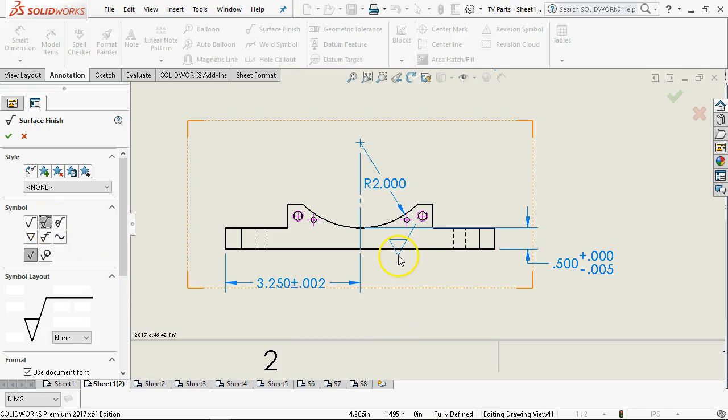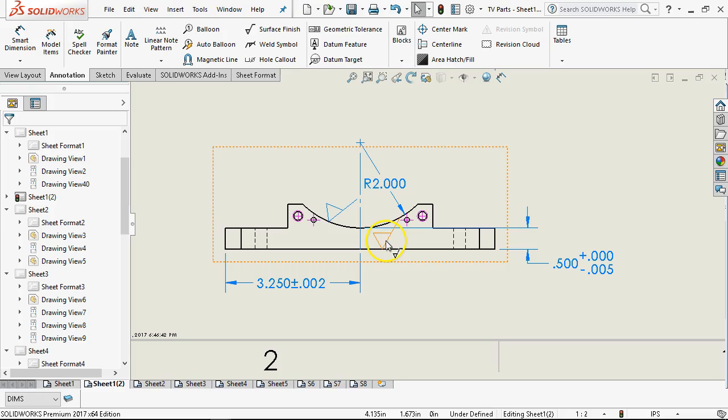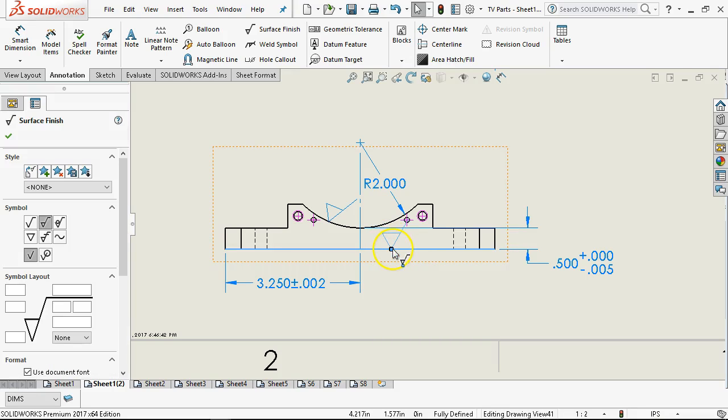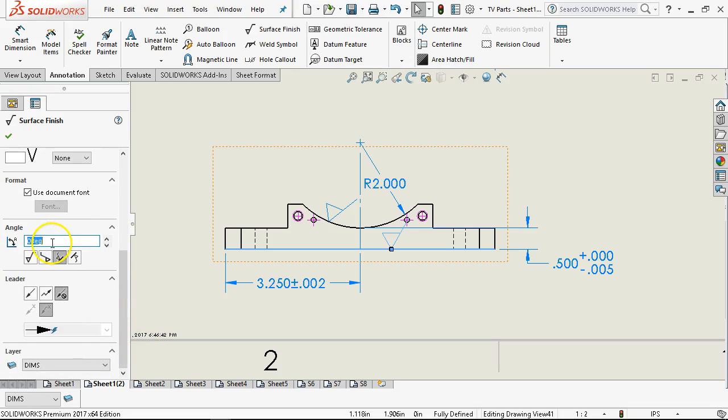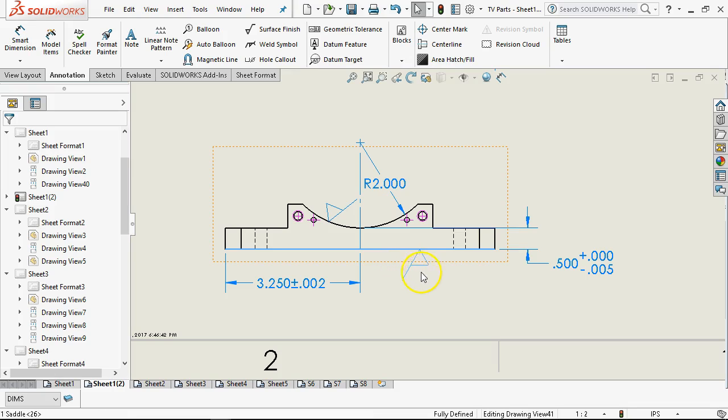All right, so machining required, and not going to go through and pick out all of those items, but we are going to pick up the grind on that face. Let's see. There's the angle. Oh, perpendicular reversed. All right, so 180. And so those will be our two grind surfaces with their finished dimensions.